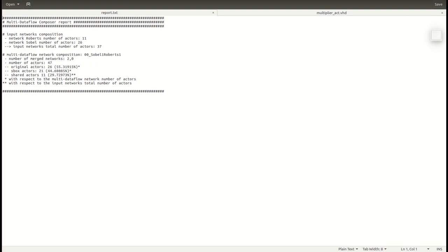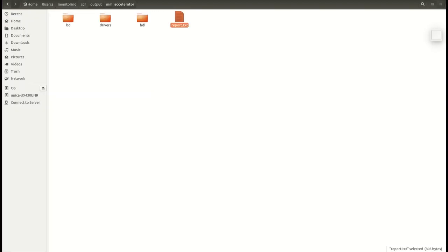The script subfolder in the accelerator generation output folder provides scripts to easily and quickly use the system in practice. The generate_ip.tcl script is in charge of generating the accelerator Xilinx IP. The generate_top.tcl script is in charge of generating the integrated processor-coprocessor system.